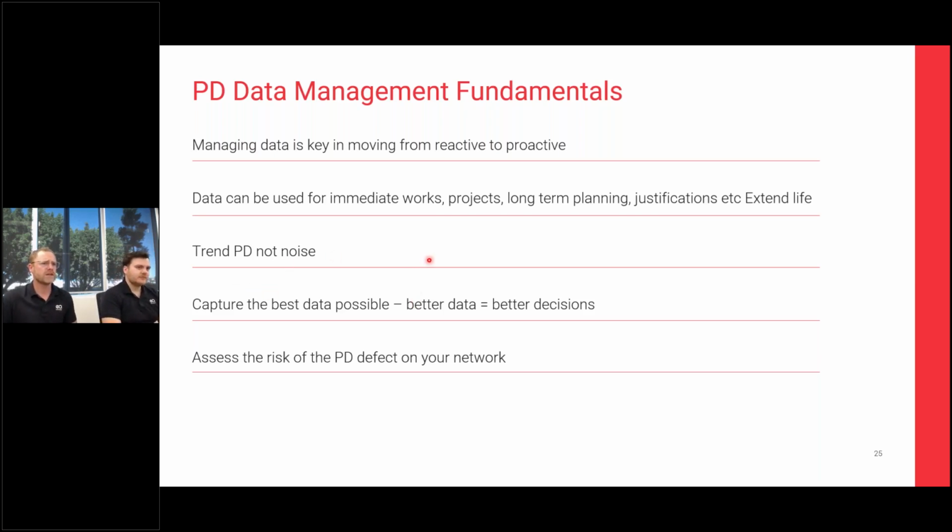Now, capture the best data possible. Better data equals better decisions. So with the new managed surveys cloud software, you can control where the people in the field are taking their tests. As Thomas said before, you'll design a switchboard, you'll design the work that you want conducted on that switchboard, and what that means is where do you want them to take a TEV reading? Where do you want them to take an ultrasonic reading? Where do you want them to take a cable PD reading, an HFCT reading? Then that is controlled back in the office.